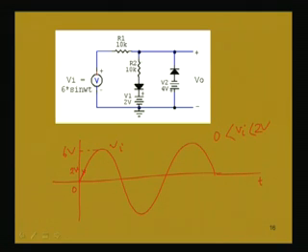So, the current will be flowing in this direction; this point is positive, this point is negative. With respect to this ground point, what will be the voltage that is asked? This is 2 volt plus I into R2. So, with respect to this point, the whole voltage across these 2 points is 2 volt plus I into R2. Now, what is I? That has to be found out.